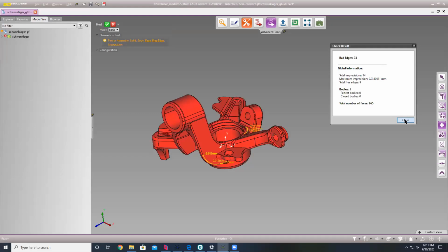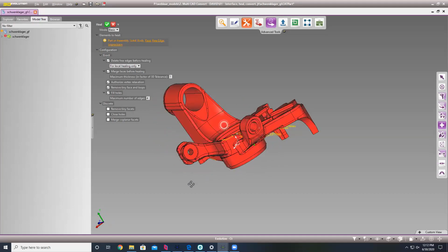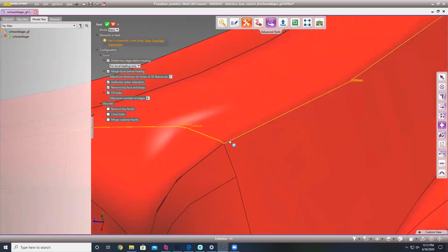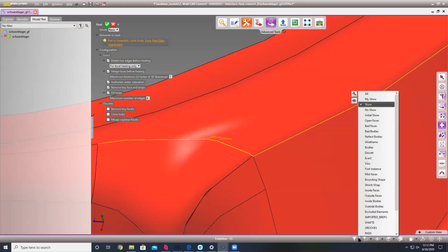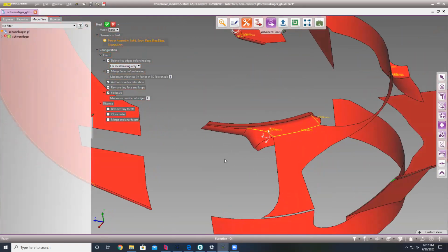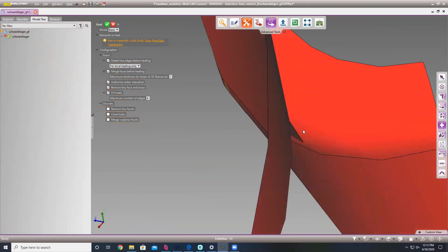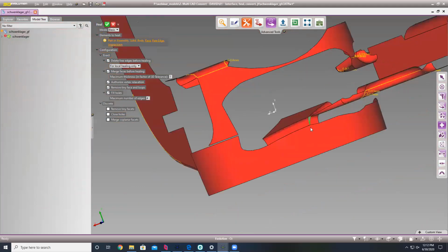I'm going to go to configurations and see if I can clean this up the same way our interface is. And we're going to go in and say, as an example, we can change the fill holes, so maximum number of holes of 4. And can you zoom into a couple of those areas and let's filter for that? So let's do a filter for bad faces in the model from an interactive standpoint. And you can go in close and see exactly where the imprecisions are on your screen. And then if you also notice, there's some free edges there with some open faces, Marco, in yellow.